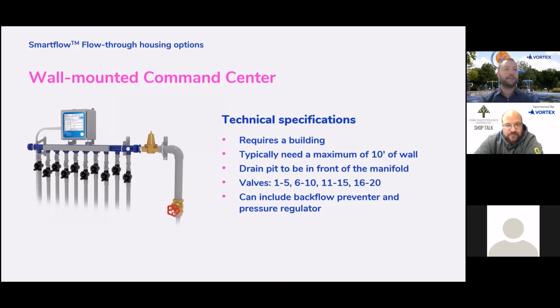Especially if you have all ground sprays, or features low to the ground, even though they're above ground features, but they're short. If we have that type of splash pad, 40 psi is perfectly fine. It's when we have 10, 12, 14 foot features that we want to make sure we're achieving that 45 psi.